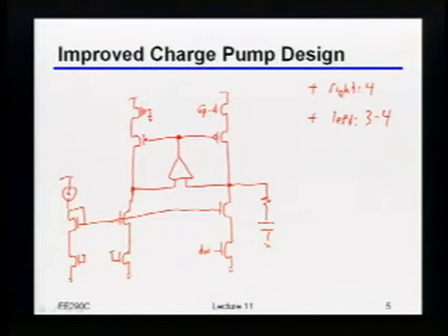Okay, but in this particular context, what is it that you care about in terms of what's going to determine which gain is larger? The voltages on the two ends. Right, so you're absolutely right that procedurally you break the feedback, you insert a signal one way and you measure what happens on that side. You break the feedback, you insert a signal the other way, you measure what happens on that side. But intuitively, everything here should be matched, right? It's the output filter. But you have some loading, yeah. What about the filter? What's important about that?